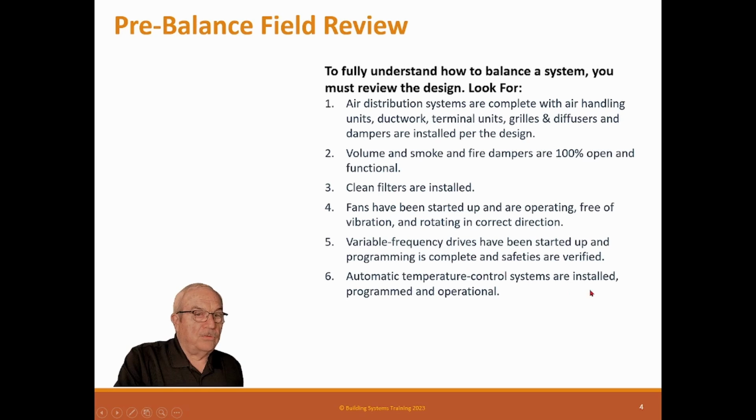Automatic temperature controls are installed, programmed, and operational. Now, I know that this may not always happen. They need you to balance the job, and the control guy's not done. Well, that's fine, but you must be able to change valves, damper positions, start and stop equipment. You must be able to do that through the controls. If not, then it's not ready for you to balance.